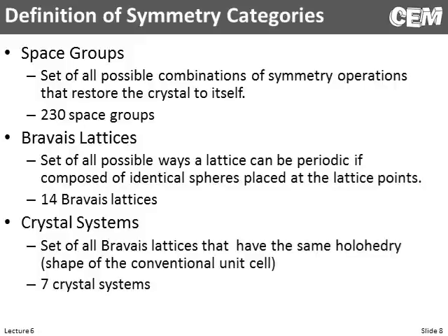spiral structures, etc. To call it a Bravais lattice, we're going to assume that it is a collection of spheres. And if it's not, a lot of times the analogy still holds. Instead of an arrangement of triangles, we'll say it's an arrangement of spheres. But anyway, if we can just say we have an arrangement of spheres, all of these 230 space groups reduce down to the 14 Bravais lattices. And we can also then divide it also into 7 crystal systems, as you'll see. That's the next slide.